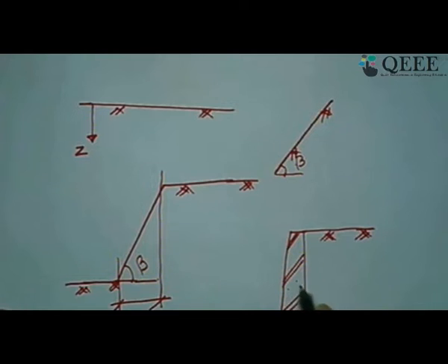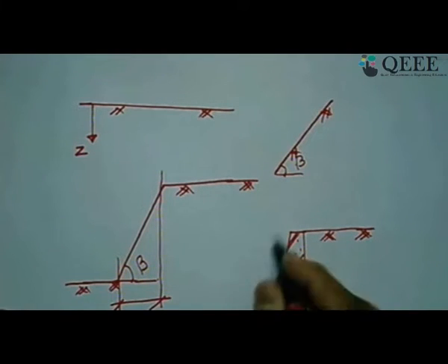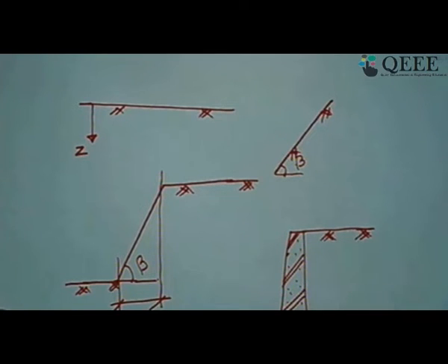This kind of construction can be of masonry, can be of concrete, any kind of rigid material. This kind of structure which provides support to maintain a level difference of ground is nothing other than what we can call a retaining structure. Coming back to this slide, you can see that at some locations, due to the limitation of space, it is not possible to provide that flat slope, that is, whatever horizontal extra distance you require cannot be provided at the site. In such cases, a retaining structure is essential to provide lateral support to that soil mass. That is what I have shown just now to you.